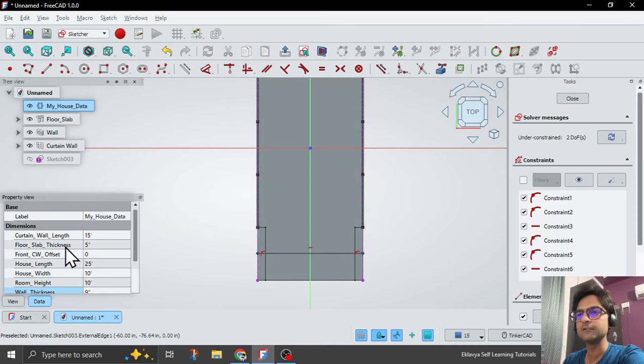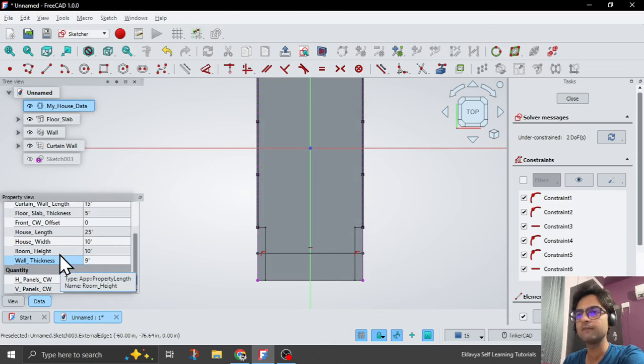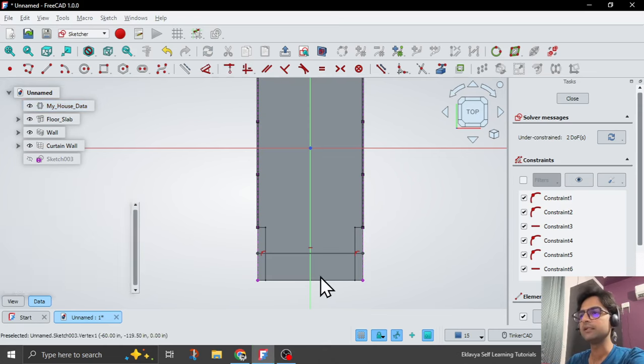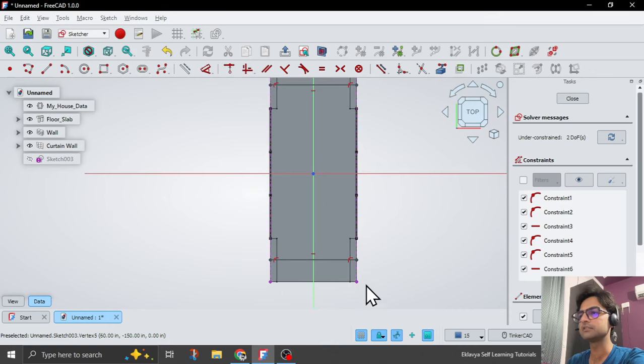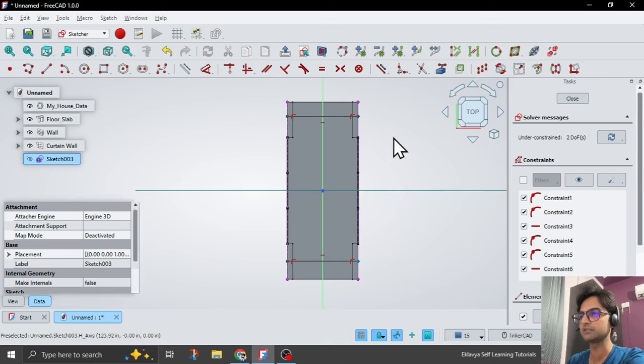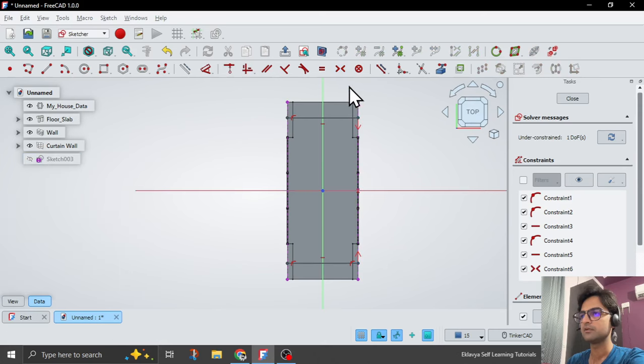And this one we will give around 2 feet. Works well. And one more thing, just to avoid mentioning dimensions 2 times, because for both of them we want the same offset, I'll make them an equality constraint along the x-axis, because all of our sketch is basically like this, right?